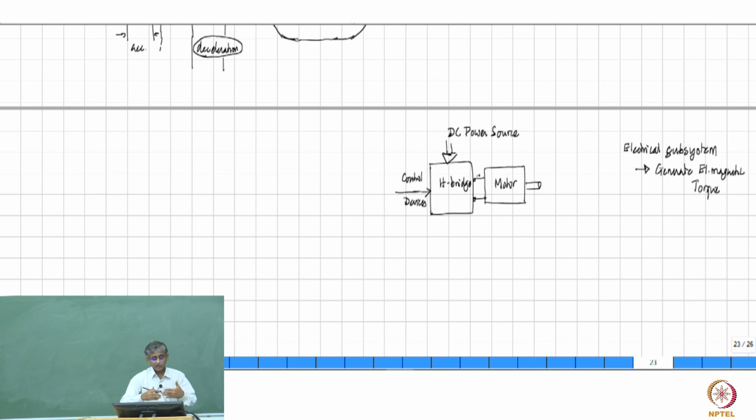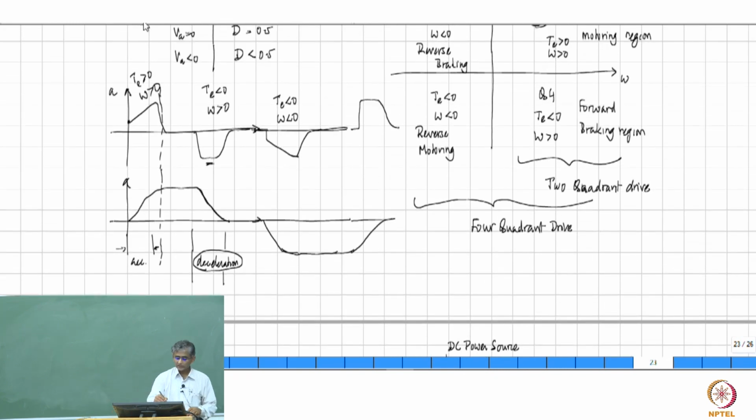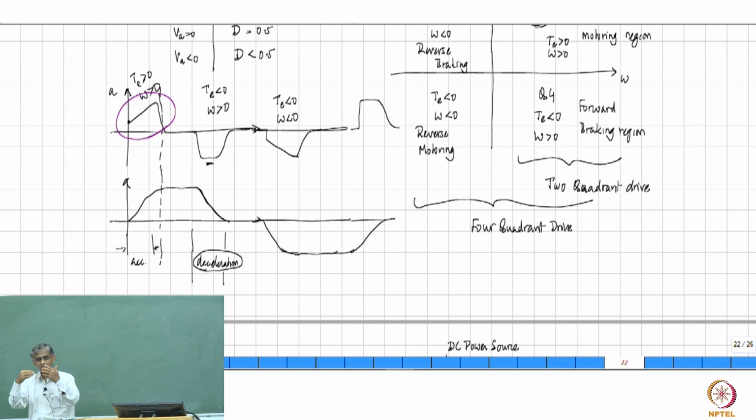If you look at the behavior of the motor itself, in order to make it move, the first thing that it has to generate is an acceleration. If it cannot generate an acceleration, there is no way the rotor is going to rotate. And therefore, if you want to control the movement of the motor, the first variable that you need to control is the acceleration or the electromagnetic forces that are happening in the machine.